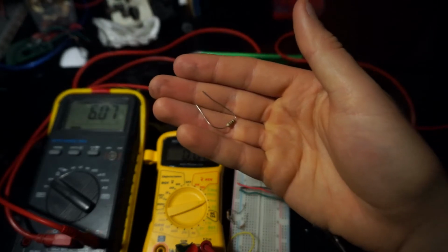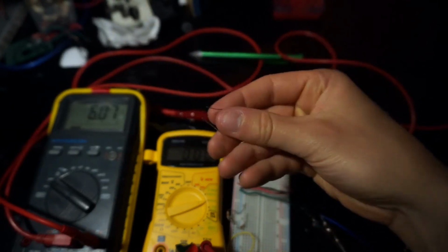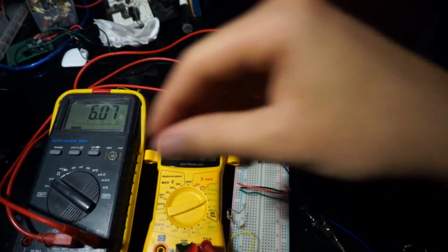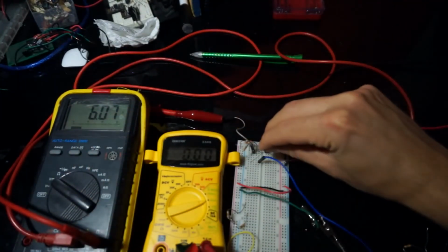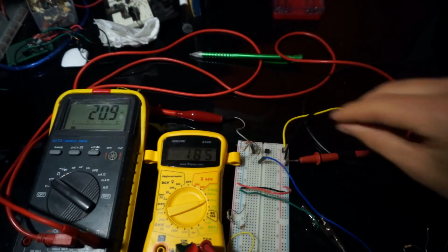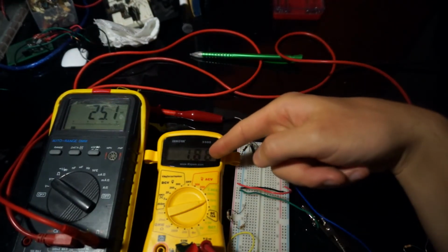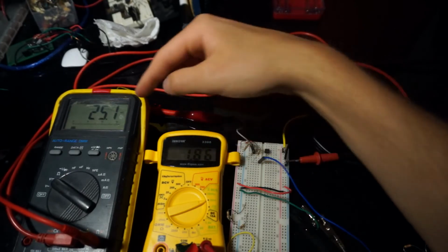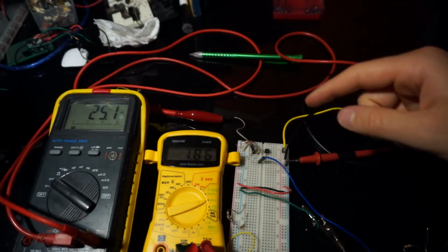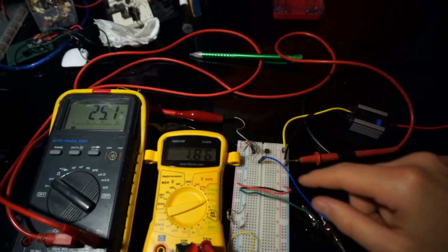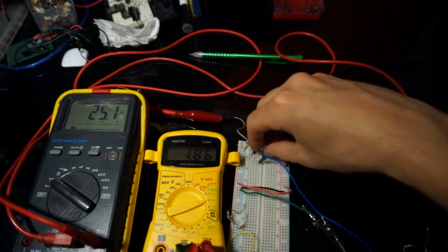We're going to start off with the 10 ohm, just to show you that it's working still. I'm probing the collector now, so I'm looking at the voltage across the load resistor. We still got the 1.86 milliamps, and we've got 25 millivolts across that, which must definitely be a little bit more than 10 ohms, but you get the idea.